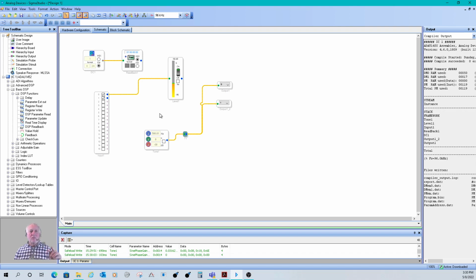But this core doesn't do that. When the interrupt comes in, it starts over again at the beginning of the program. So what that means is it doesn't reach some code, and so all of a sudden an output's not working, or something else is not working, a meter's not working. It's because it's never being reached. But that's again another discussion.